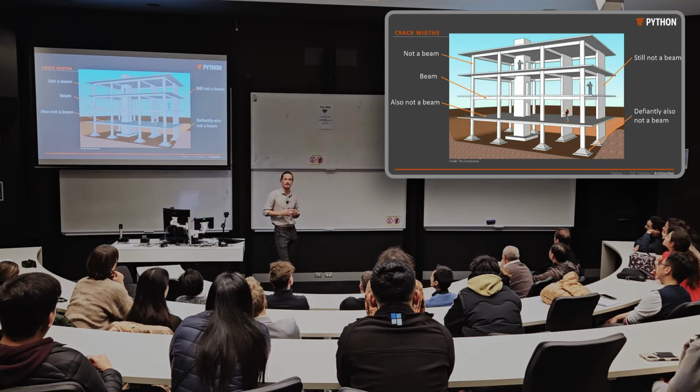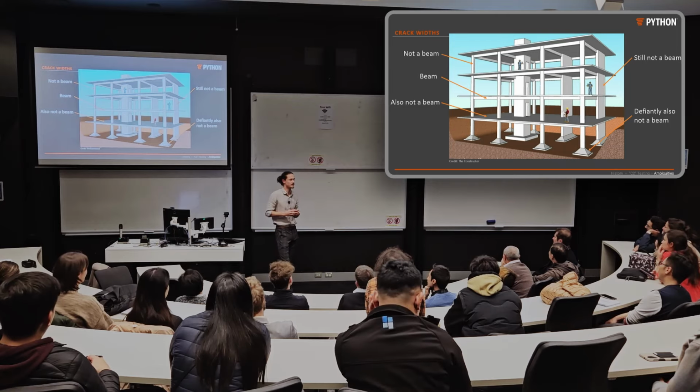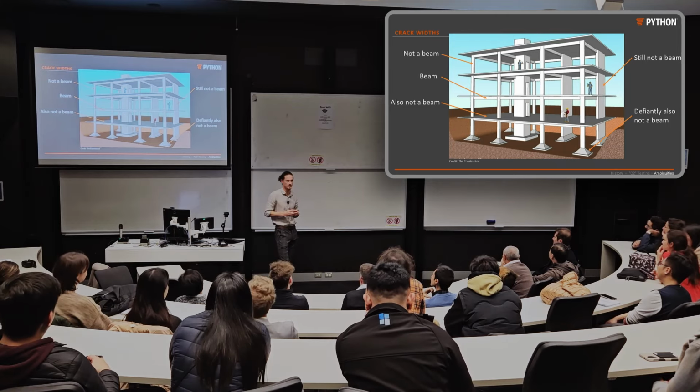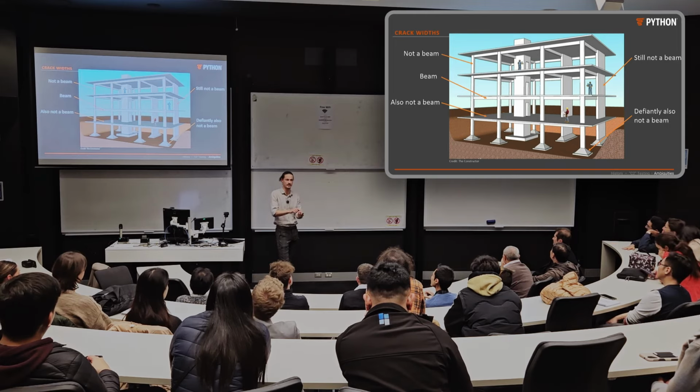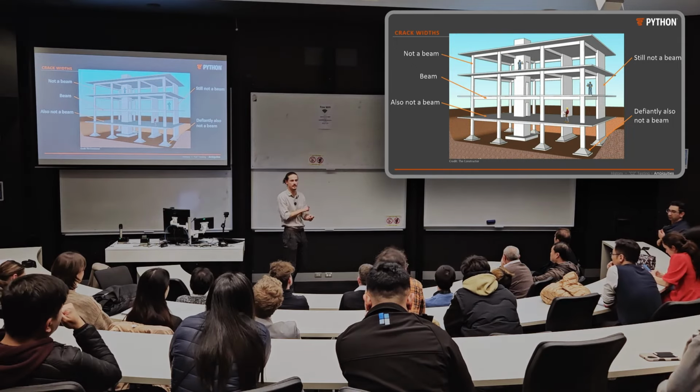And so it is not necessarily the case that crack behavior in beams is reflective of things like shear walls or things like columns. Maybe it is. Fundamentally, we're allowing for that 0.5 and 0.8. That is fundamentally what that capacity represents. But I am not sure how well that represents other elements in a reinforced concrete structure.